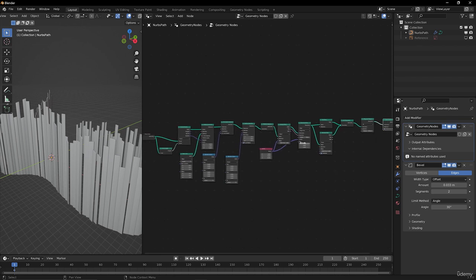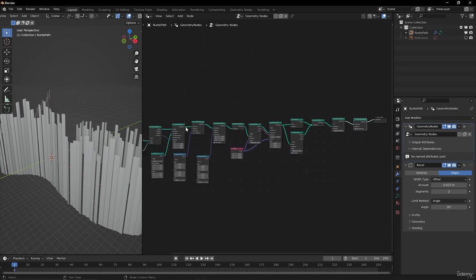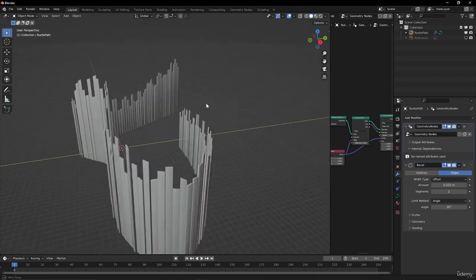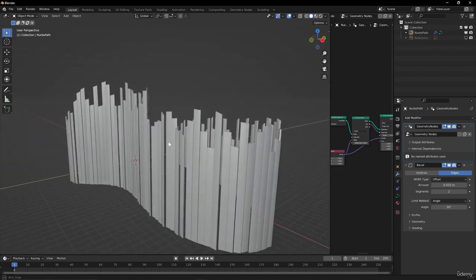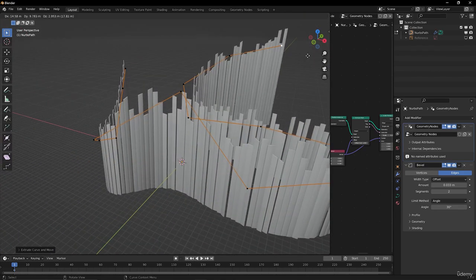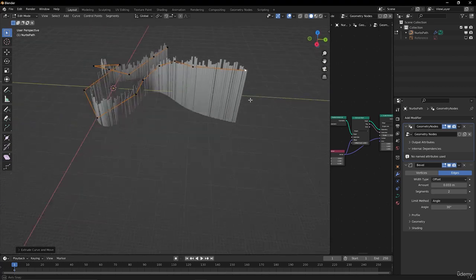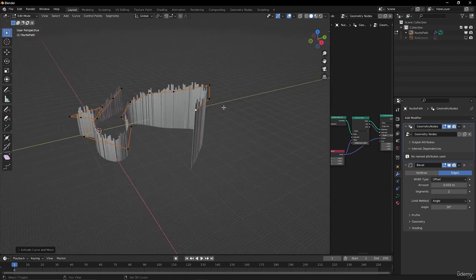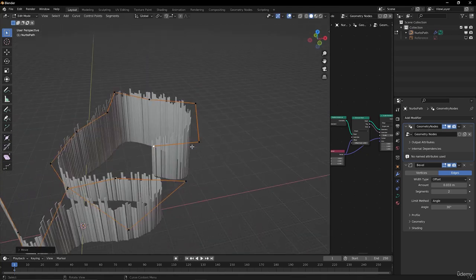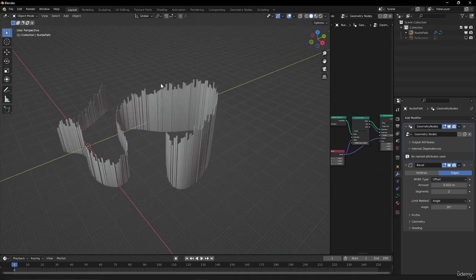It's a bit more complicated than the chain, for example, but you can see how you can treat your curves and instances to achieve things like this. And it's pretty nice. Now you can just extrude your curve wherever you want, and you can have unlimited and perfectly fitting planks around it like this. So this was the example for the fence.